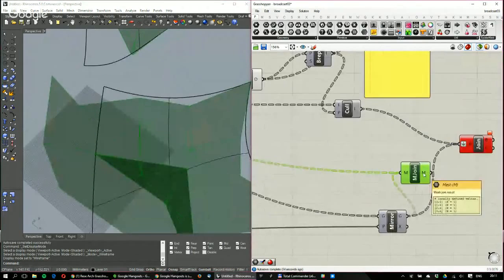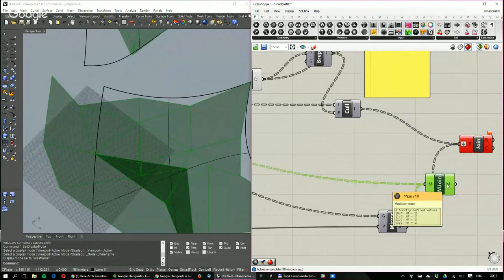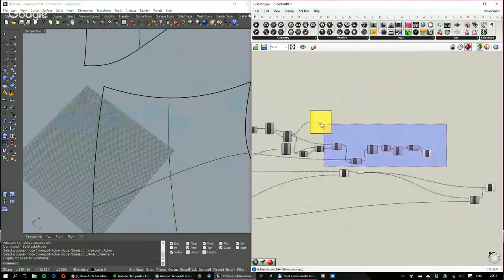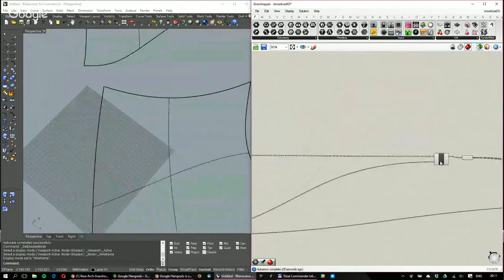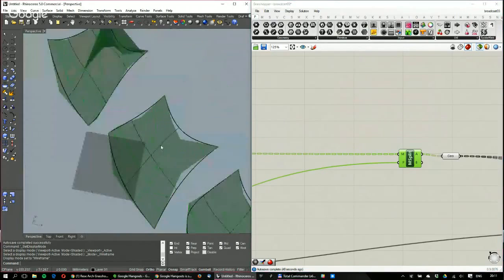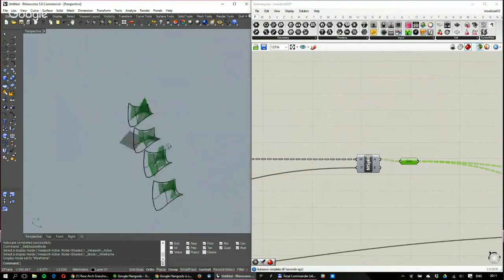Now we have two meshes. We have two meshes in each branch. We ended up having one. So I can completely delete all the logic here, only because there is this beautiful, beautiful component called mesh split with a plane. If there wasn't, we would have to sort faces and realize which face is inside, which one is outside of the bounding box. But you probably get the idea with sorting those faces already, because we've done that with the B-reps or surfaces.